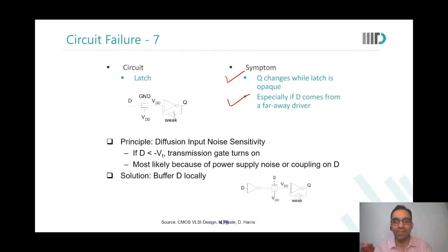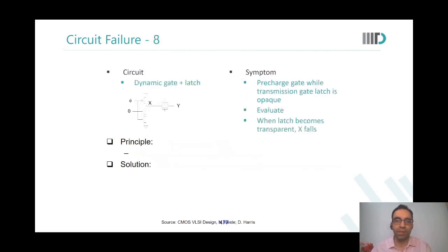Sir, could you explain why it is going to -500 millivolts? So there's a floating node somewhere. Some crosstalk came. It can take it to whatever level. It can be a positive or negative signal. It doesn't depend on that. Let us say it was stored as 1. A positive crosstalk came. It will take it to 2 volts. Again, the same problem would happen.